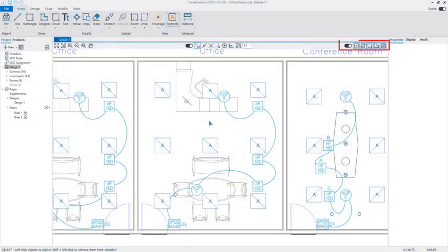And on the right side of the toolbar are selection filters, which limit the object types you can select for modification. For example, deselecting the product selection filter will prevent you from selecting luminaires and controls, generating a message below when trying to select the objects.